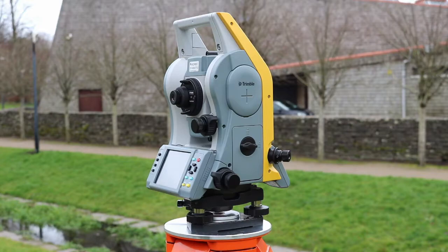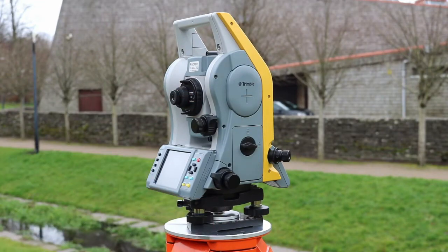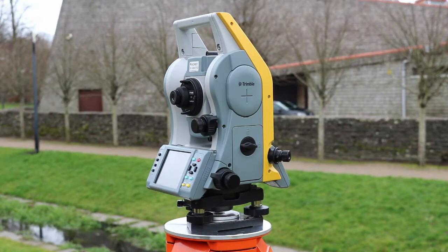Once this is done, you can then lock the slow movement wheels in place in both the horizontal and vertical planes. The locks are located here at the slow movement wheels. The locks only allow slow movement wheel motions. It restricts the swivel motions, allowing you to more accurately move the crosshair in position.